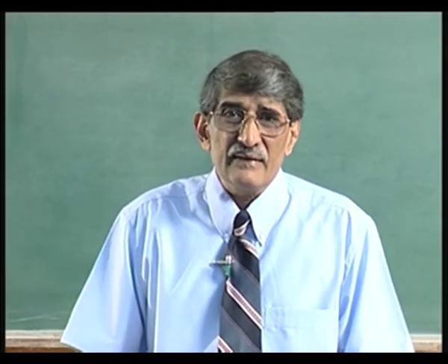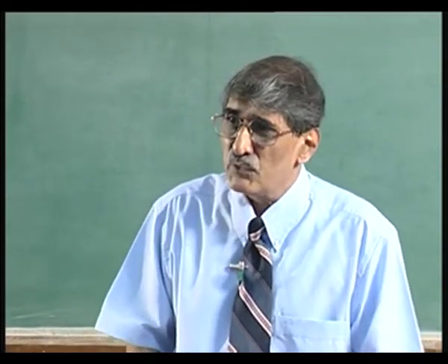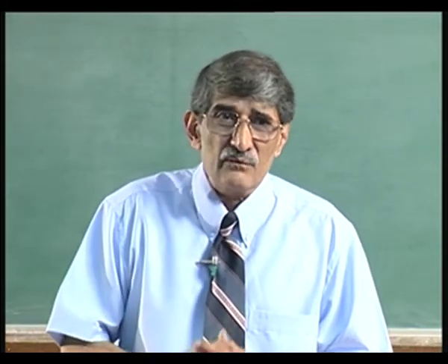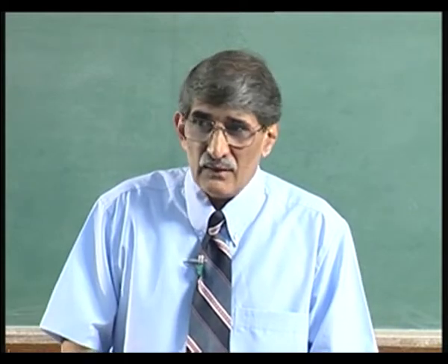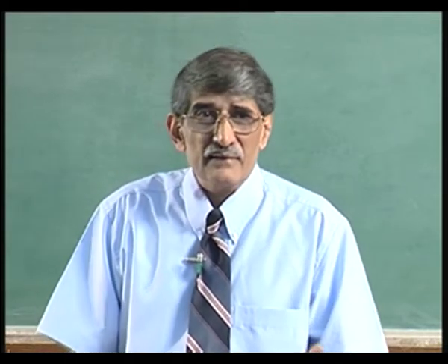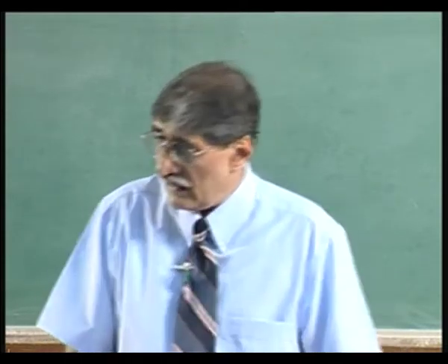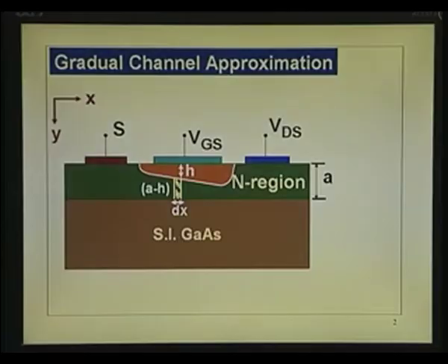In fact, the electric field increases, because what we have used is the equation J is equal to Q n into V. Now, area falls, so V increases and the electric field increases, and when you reach this end, you will have velocity saturation. We discussed this last time. The real saturation is due to velocity saturation at this end.